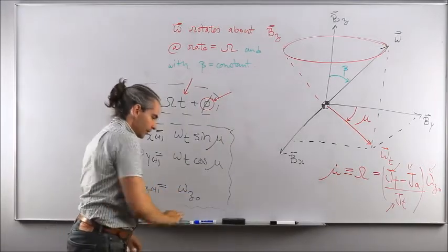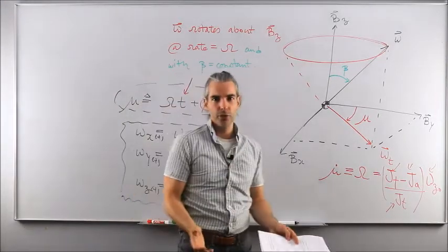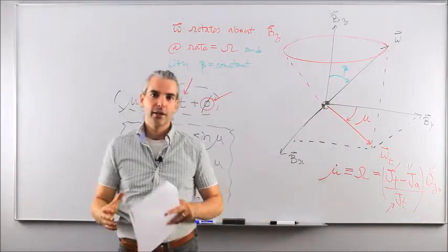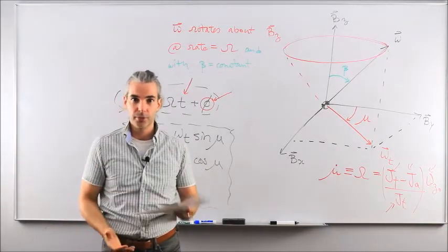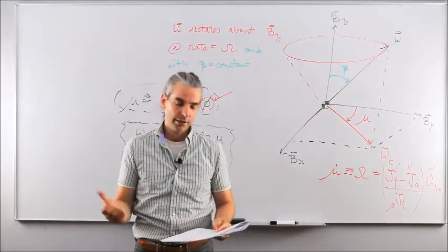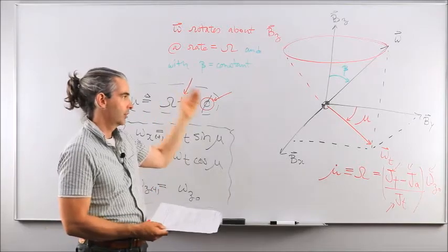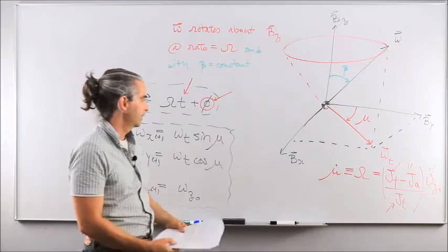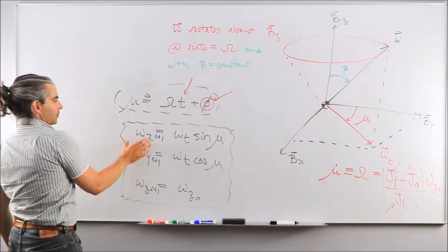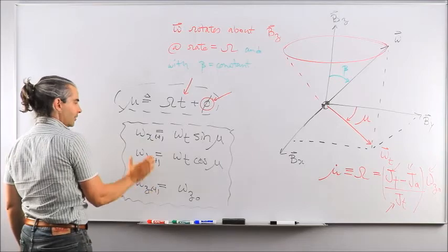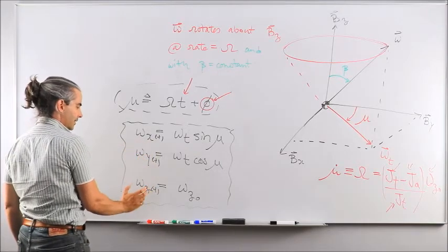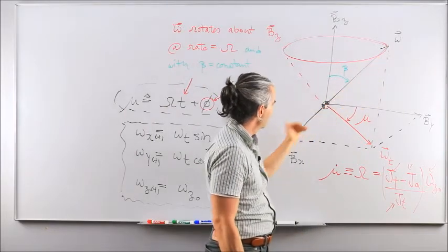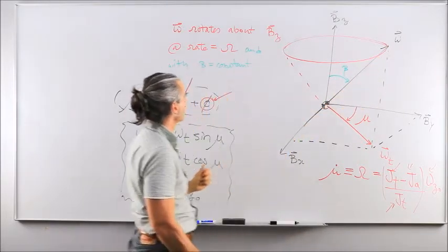Isn't that beautiful? We went from Euler's equations of motion, took some simplifying assumptions on the geometry of the spacecraft and on the environment in which the spacecraft is spinning in, i.e. the torque-free assumption. And then we just derived the equations. We applied the Laplace Transform, the inverse Laplace Transform, and ended up with what we were seeking, and that is analytical expressions for x, y, z components of this angular velocity vector inside the body fixed reference frame. Okay.